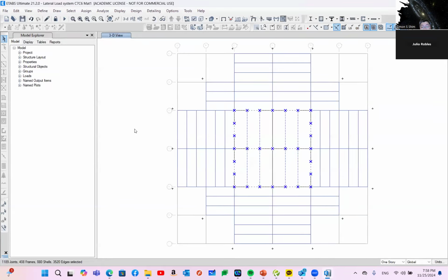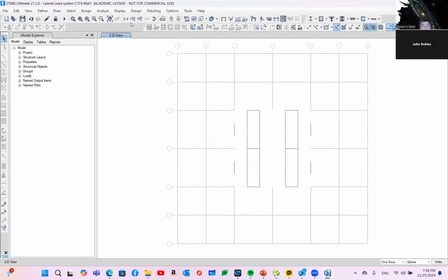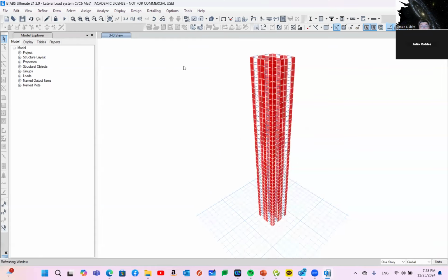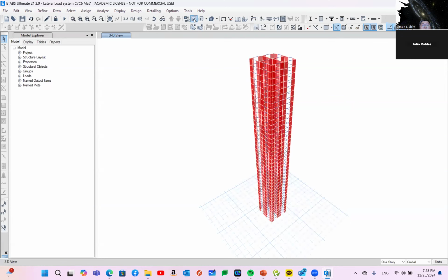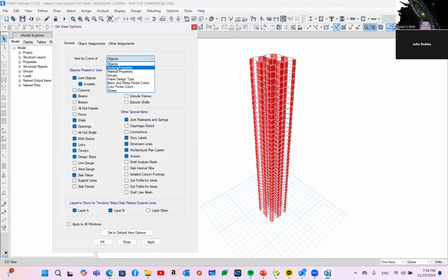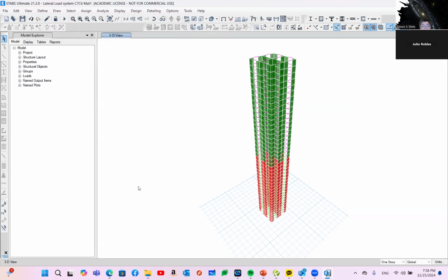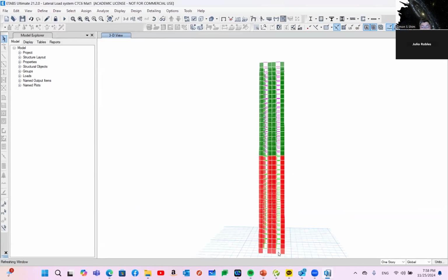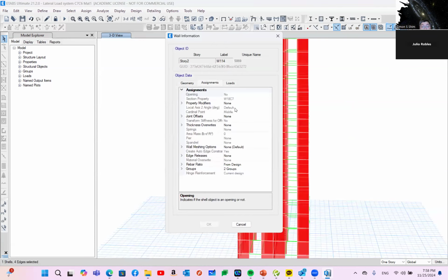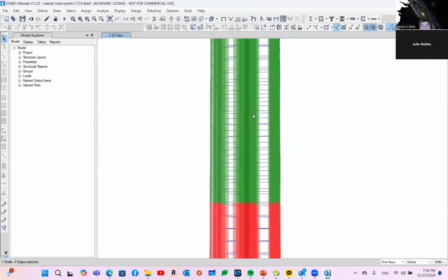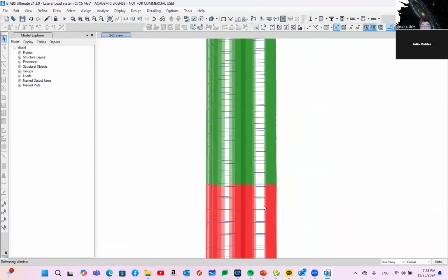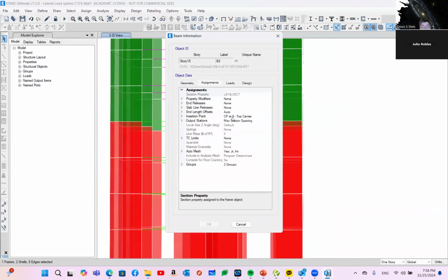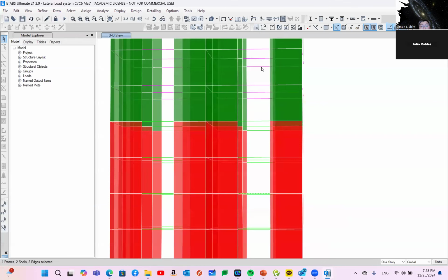I'm going to select all these 3D members, show only members, and so Control D. Okay, wow. So I only select all the wall and beam. Now you said you assigned two different sizes. Okay, good. So basically you cut it in half, 18, 16, and 6. And the link beam here, you're matching the thickness? Yes, 18 by 30. Okay, things for now look good.